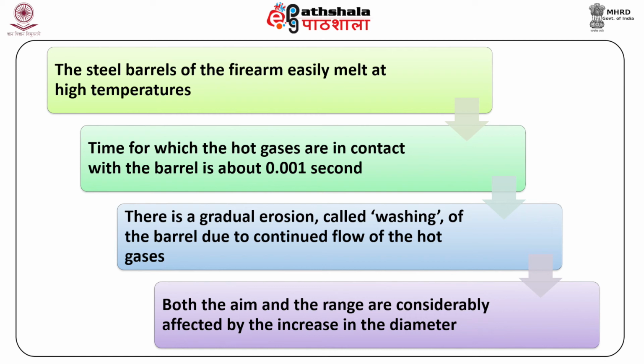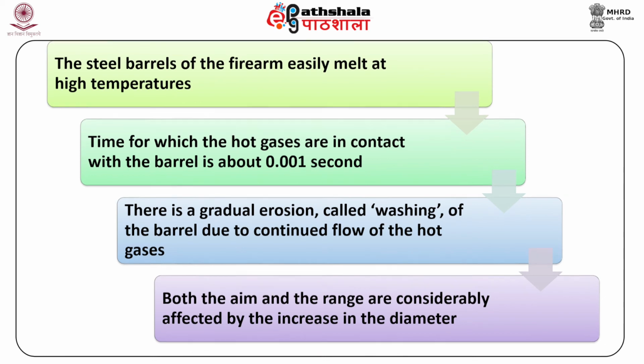Instead, there is a gradual erosion called washing of the barrel due to continued flow of the hot gases. They carry away metal slowly but surely. Both the aim and the range are considerably affected by the increase in the diameter.